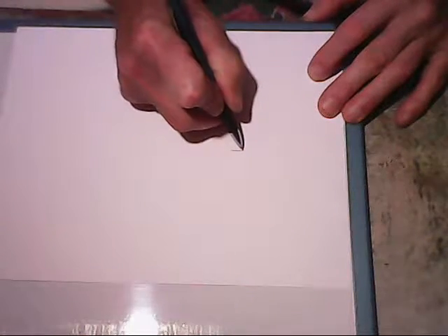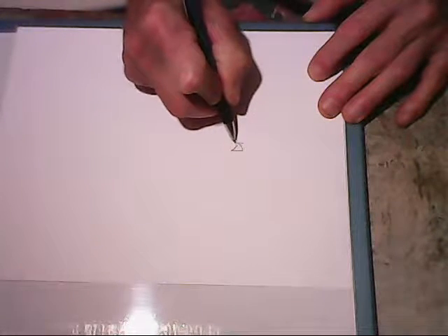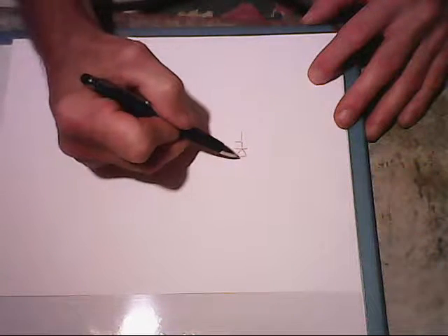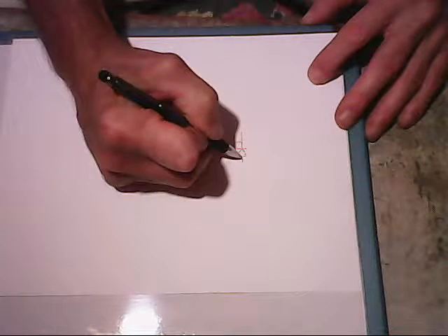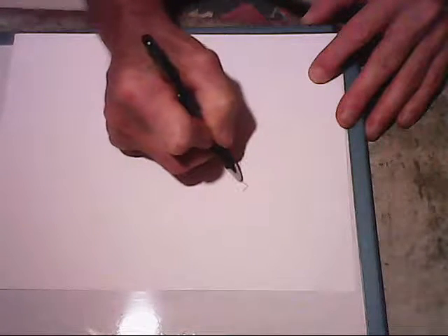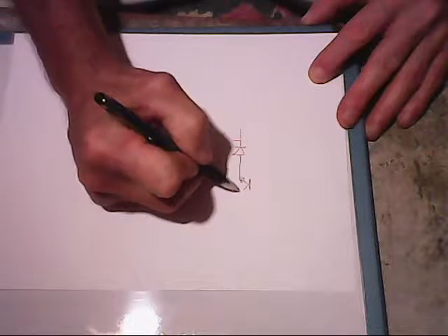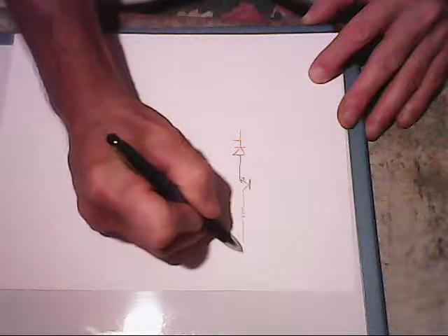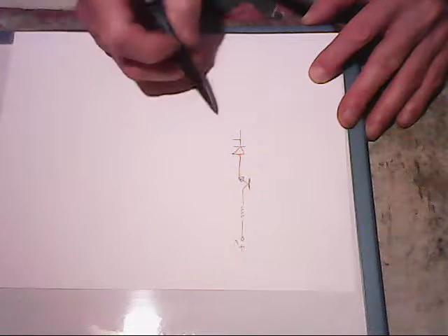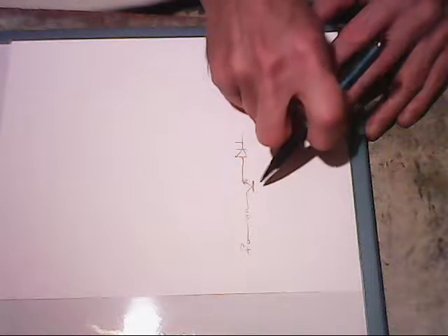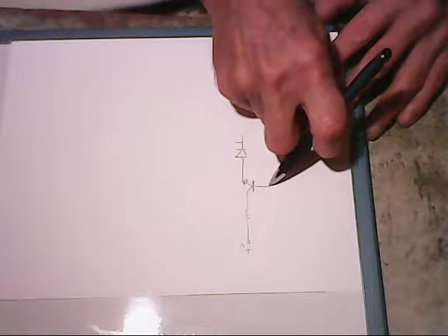so let's start out with an SCR. If I use an SCR here, I need a way to turn the SCR off. So what I'll have to do is put a transistor in here, an NPN transistor. And then we'll put a current limiting resistor to the positive side of the battery. Then I'll need a way, as I said, in order to turn this SCR off, I'll have to be able to turn the transistor off.